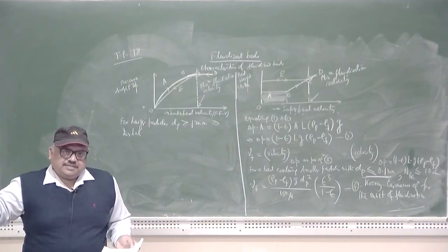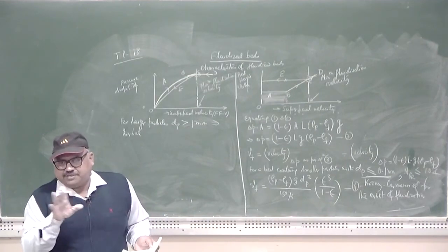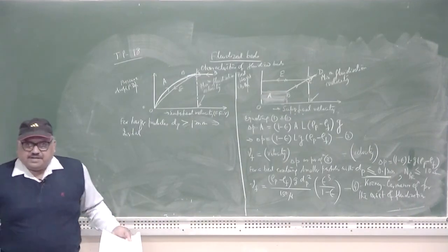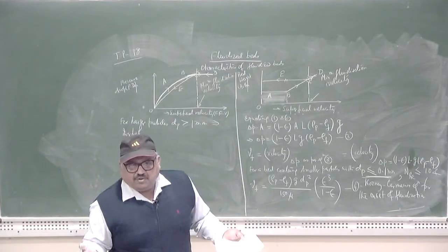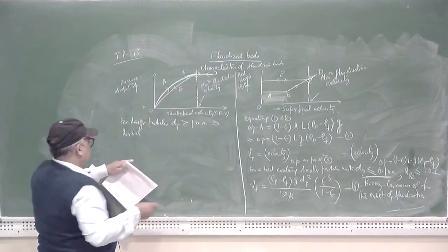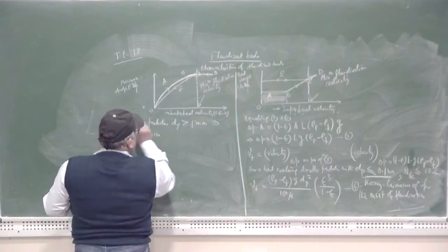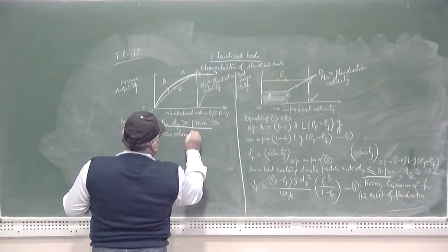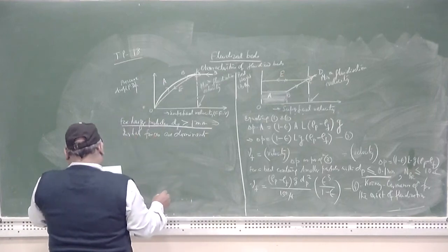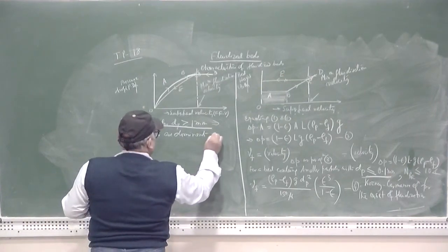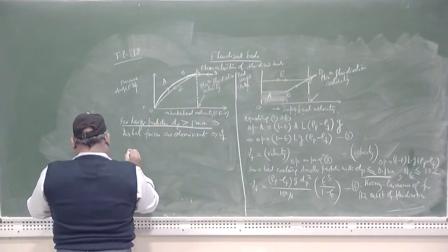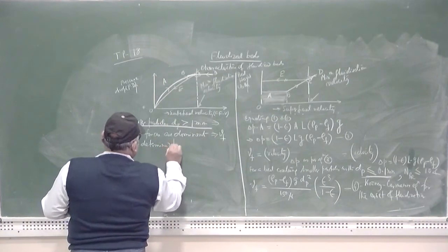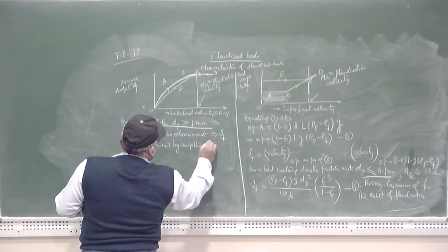This is the possibility under which the Reynolds number can increase, because the viscosity of the system cannot be altered in the present situation. So the only thing that can be altered is the inertial force. If it can be increased by having a larger volume equivalent diameter, then the inertial force may be increased. So here, if I am considering a larger particle with dP greater than 1 mm, it means inertial forces are dominant. So in this case Vf can be determined by using the full Ergun equation.